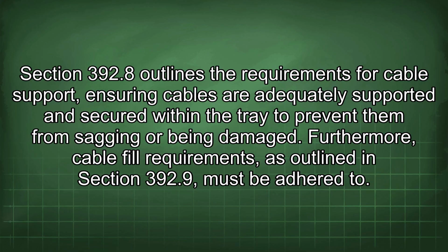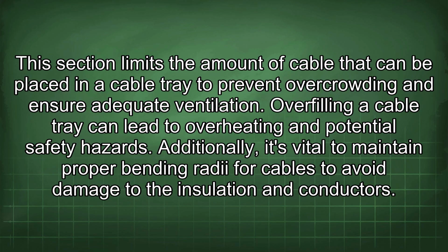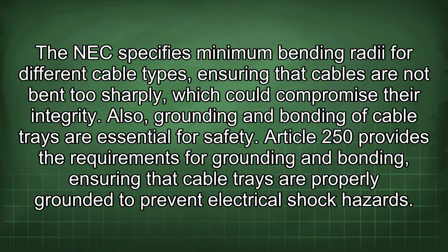Furthermore, cable fill requirements, as outlined in Section 392.9, must be adhered to. This section limits the amount of cable that can be placed in a cable tray to prevent overcrowding and ensure adequate ventilation. Overfilling a cable tray can lead to overheating and potential safety hazards. Additionally, it's vital to maintain proper bending radii for cables to avoid damage to the insulation and conductors. The NEC specifies minimum bending radii for different cable types, ensuring that cables are not bent too sharply, which could compromise their integrity. Also, grounding and bonding of cable trays are essential for safety.